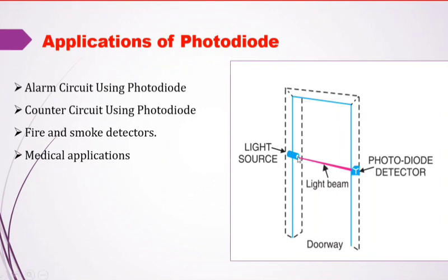If a person is standing in between the photodiode and the light source, the light is blocked by the person. So the light will not reach the photodiode, and its resistance will change. Therefore, if a dark current is showing, we can tell a person is in between. It could be an object, not a person, between the light source and the photodiode.